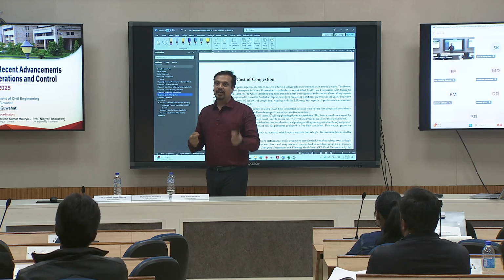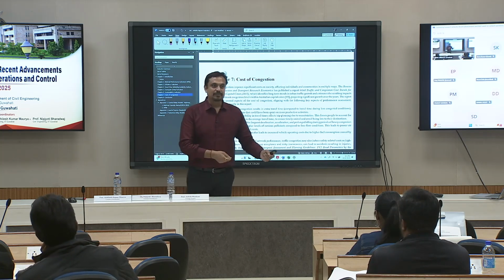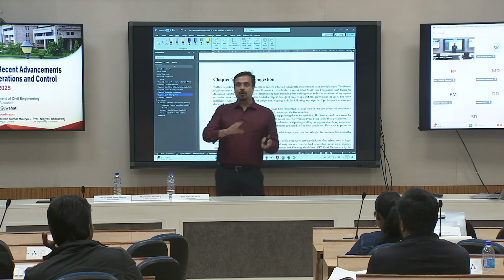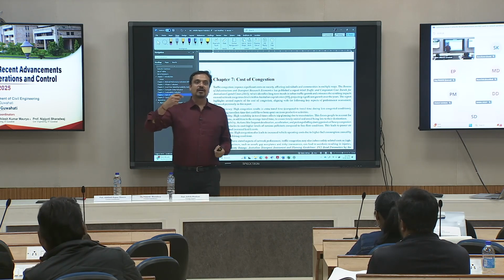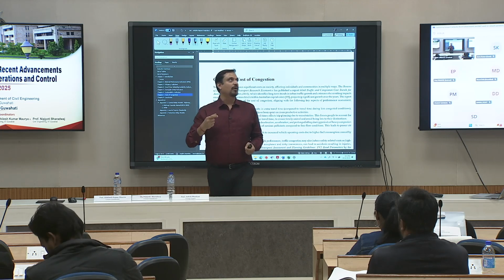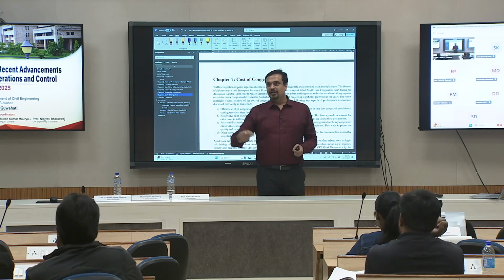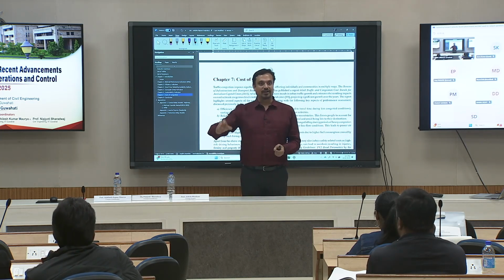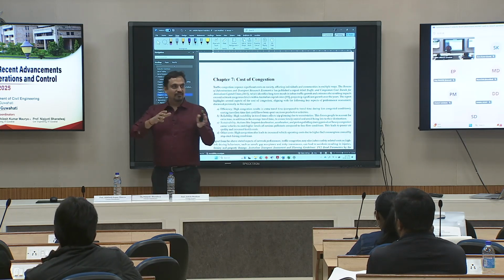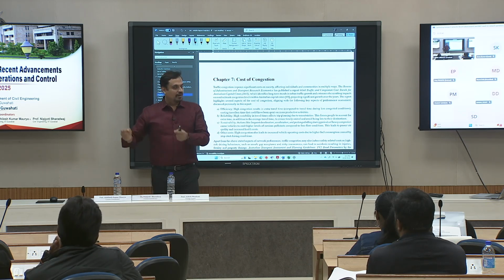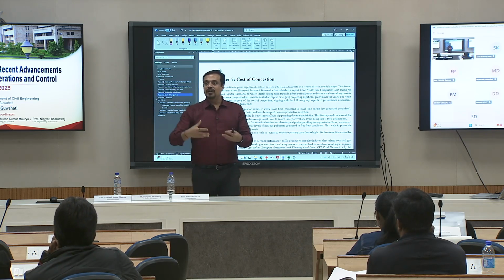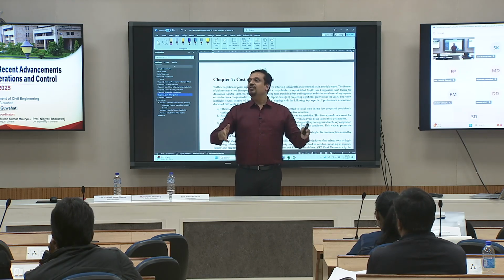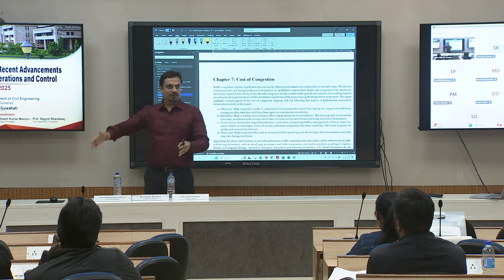You also know the value of time. You also know that maybe for this specific type of road user, that's the dollar value I'm going to specify. So you know all those things. You consider the in-vehicle occupancy rate. The cars might have an occupancy of 1.2 or 1.3, whatever you're using, and then you consider the cost accordingly. So all these econometric figures, you can bring them together. You can just simply do the calculation and get one cost of excessive delay for that corridor because of the congestion, and you sum it up over all the corridors.